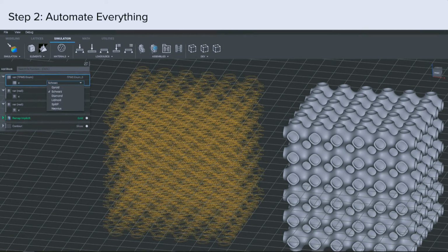Step 2, automate everything. So here is a part in our new product, nTop, along with the slicing for it. Usually the path, by the way, to go to manufacturing, especially for complex geometry, we're not using the STL anymore. It's great to do your model setup on BREP, and you can for the technologies that you can, but at some point, we're just going to produce the slices. Our customers would run into slicing triangles. It's just not worth it. And we're not the only ones who are doing this, but it's just sort of the reality that the main thing we're going to deliver is going to be some slices to the CAM system, and maybe a mesh or a simplified Parasolid model back to the CAD system so the CAD guys can see it in their context. But the real deliverable is usually slices.